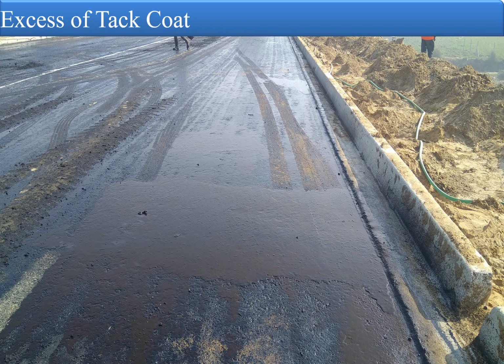So if you see some of the examples of laying a tack coat, like in the photograph, you can see there is an excess application of tack coat in one portion of the road which is being constructed. What one should do is immediately clean up this area before covering with the next layer of asphalt mixes, because if you run the mix over it, you will have a separation membrane which is thicker than the normal one, and this will ultimately lead to a slippage plane.